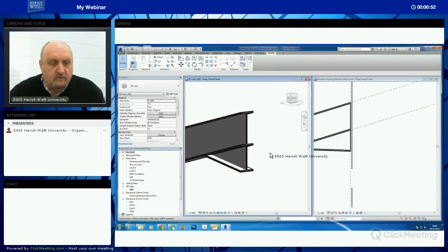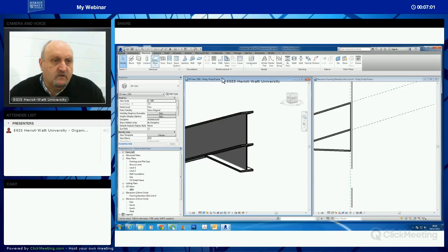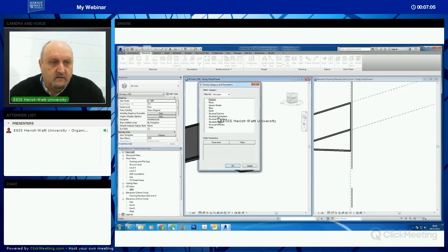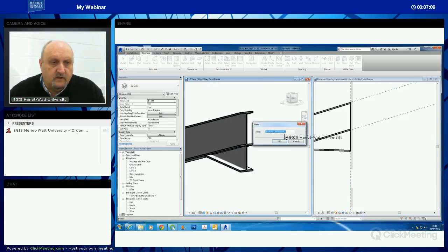And although we're doing generally model connections, I'm going to model a structural connection. And the structure is component model in place, and it's a structural connection I'm modelling. You should give it its full name. This structural connection is called a weld plate.